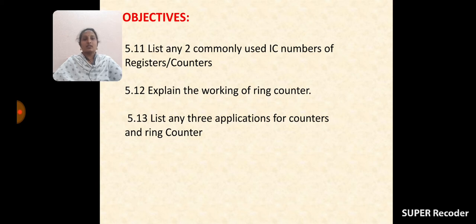In asynchronous counters, the next stage flip-flops are triggered with the output of the previous stage, so it provides more propagation delay and the asynchronous counter becomes slow. In synchronous counters, the flip-flops are triggered at the same time with the same clock pulse, so the propagation delay is reduced and the system becomes faster.